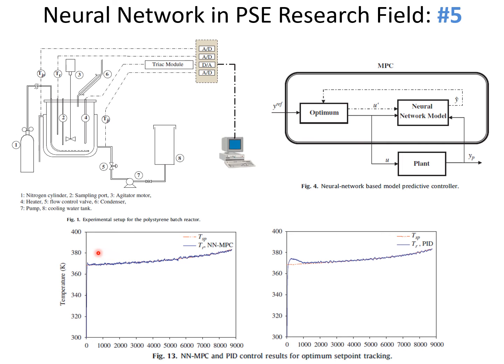And also, finally, it's able to show the advantage of this. Normally, people will say, okay, why don't you use PID? Okay, we use PID, but with PID there's an overshoot initially, later you pick it up, but this overshoot may not be acceptable in some systems. It may already spoil the polystyrene, may even spoil the product that you have. If it's too high a temperature or too low a temperature, whatever, the batch is already spoiled. So that's not acceptable in many cases.